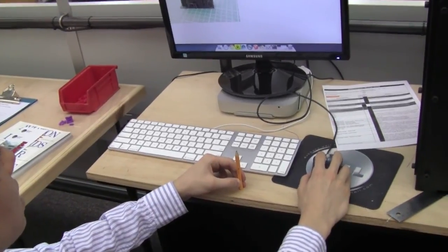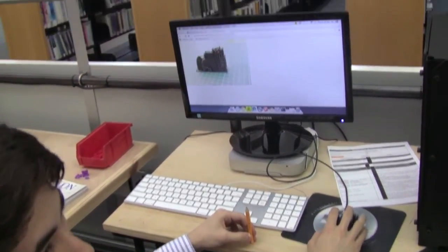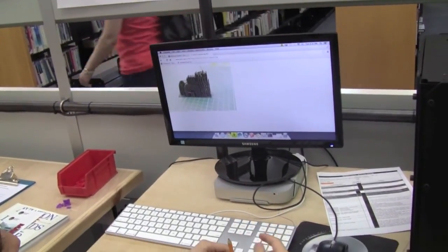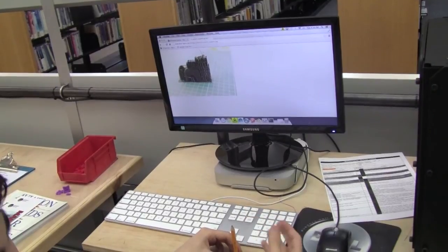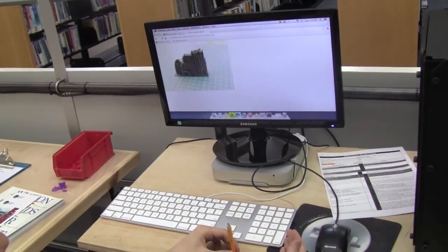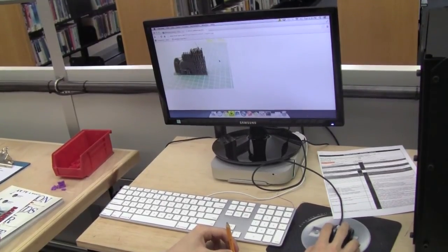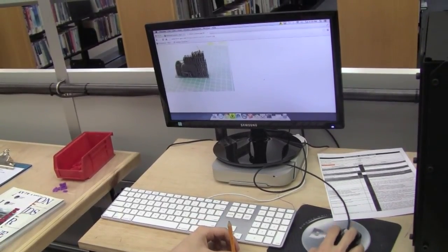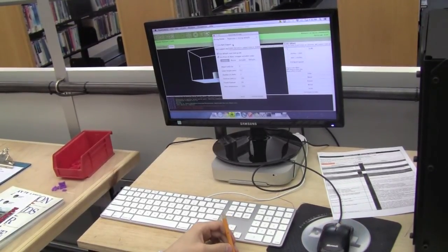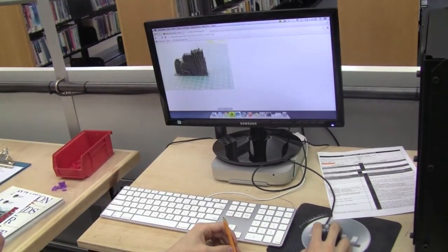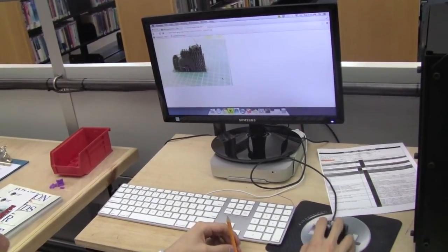And it's made such that it's really easy to remove. If you see how thin the walls are and the zigzagging structure, you can just peel it off afterwards. There might be some visible marks on your model, but generally you can sand them off, clean it up, and it'll let you print your object. The only problem with support is that it'll take a lot longer to print, so you can just see how much extra plastic that is. It might be just as much plastic as the model itself, actually.